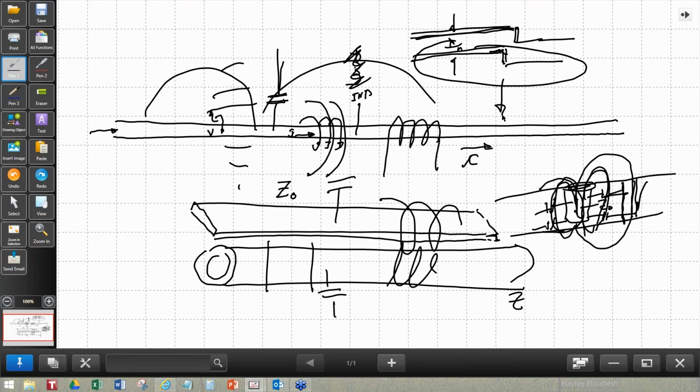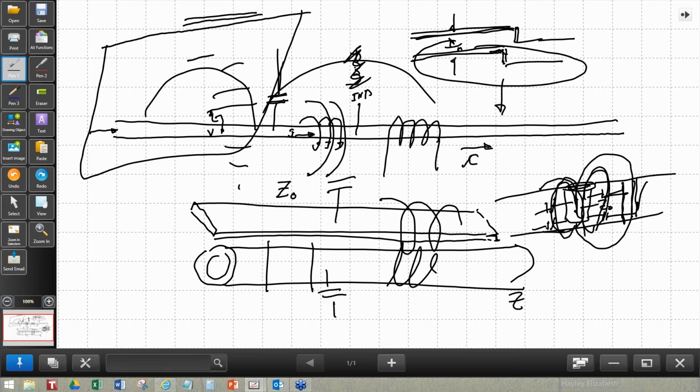Otherwise, if you take a trace and then you put a ground plane directly under it, then elsewhere on the ground plane, it can actually be closer, because this first trace will be interacting with the ground plane so intensely that very little will be left to get out and actually couple to the second trace. So proximity of things like ground planes makes a big difference.